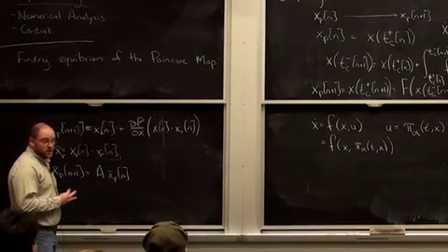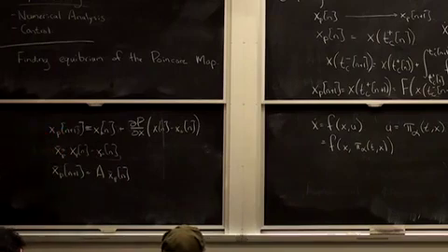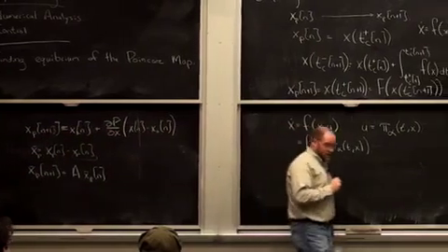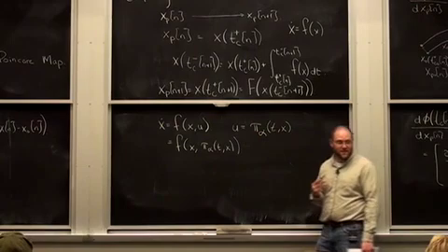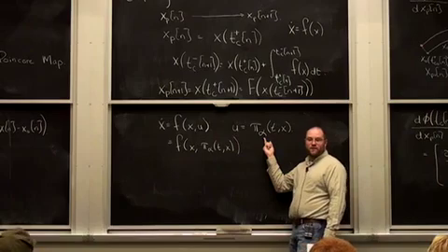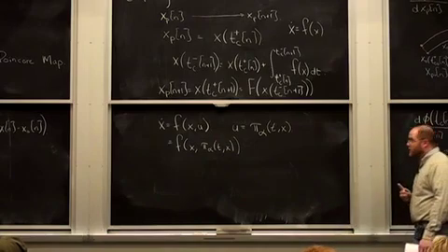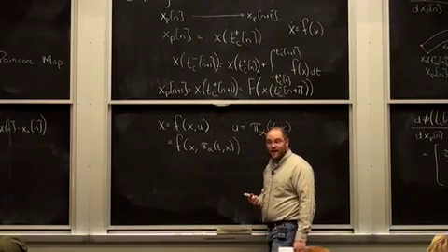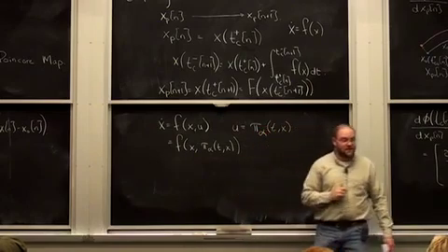There's a different way to think about control in the discrete time Poincare sense. One way to think about it is, every time I hit a surface of section, or my foot hits the ground in the walking case, I change the parameter vector alpha. I'm going to make decisions only once per step, and then execute this policy for the duration of that cycle. The next time my foot hits the ground, I'll make a different decision about alpha.